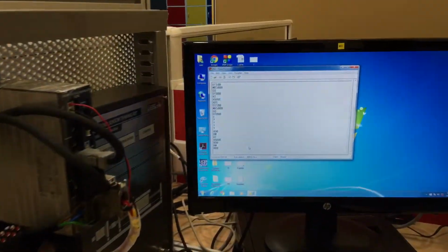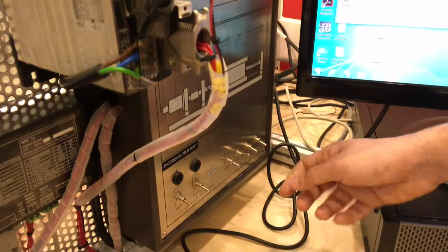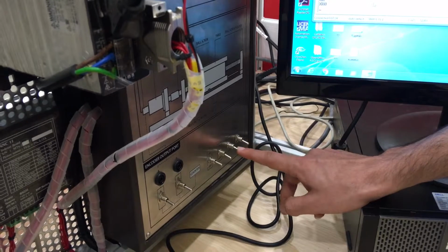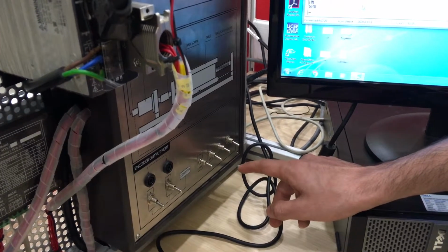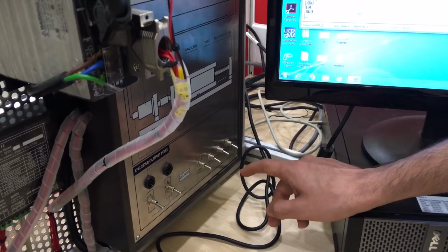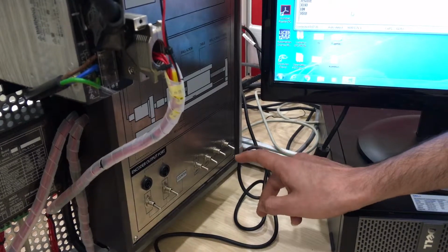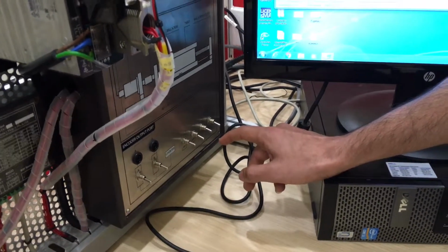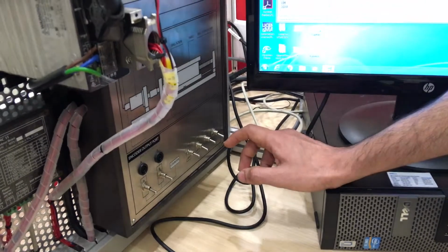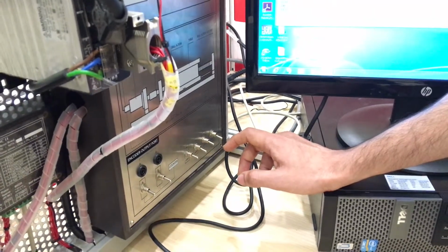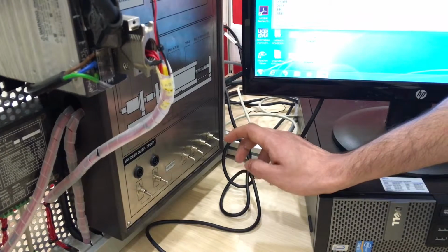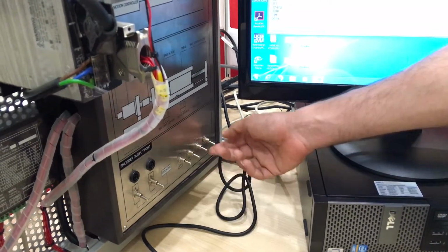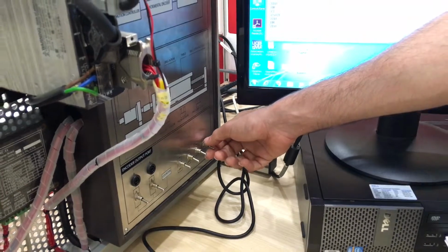Now, all of them being at the bottom means that all of them are 0. This is a very good way to actually perform home without having to include the sensor. It's just uploaded into the machine like that. So you key in all of them 0, and then you turn it on. It should actually move to home.